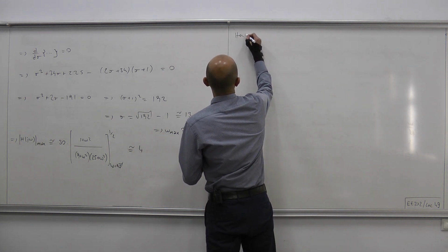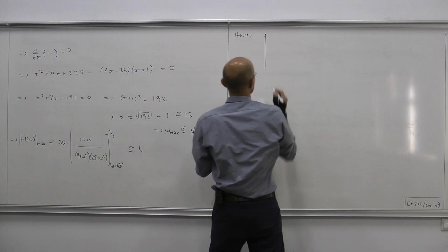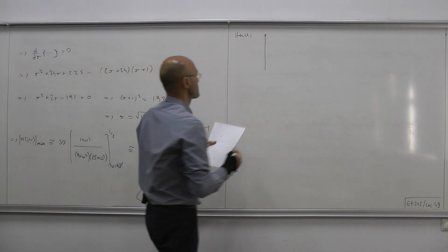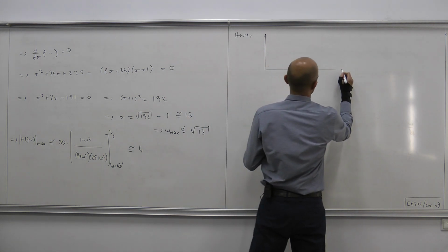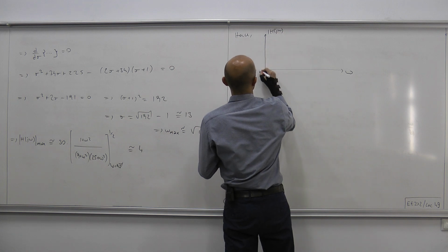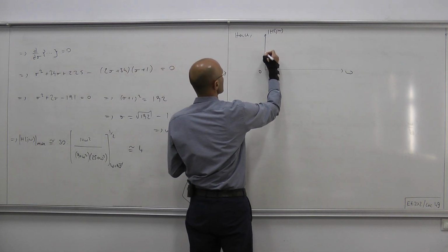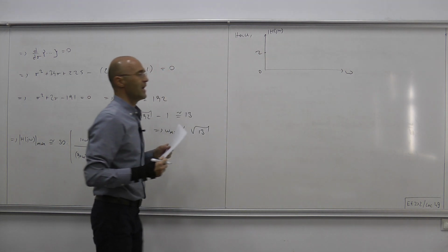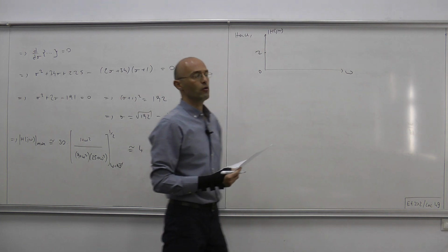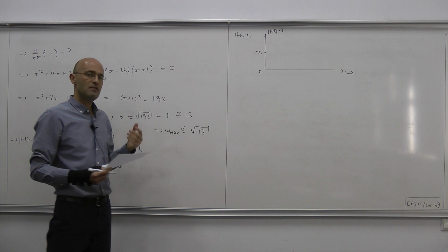Okay, so let's summarize our findings on a simple plot regarding the gain. Axes: ω and |H(jω)|. We start from 2, and we're heading toward 0 as ω goes to infinity, but we're doing that in a non-monotonic fashion.